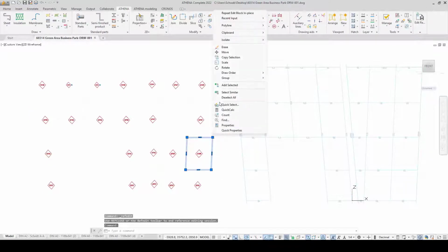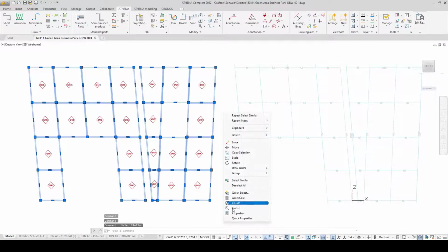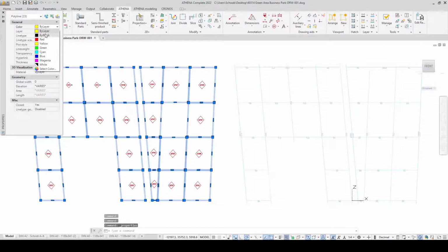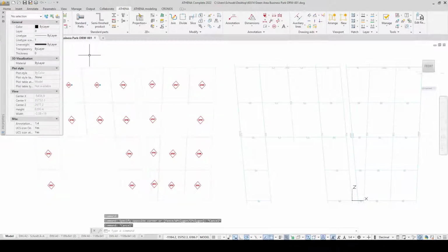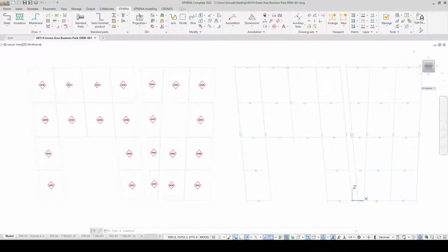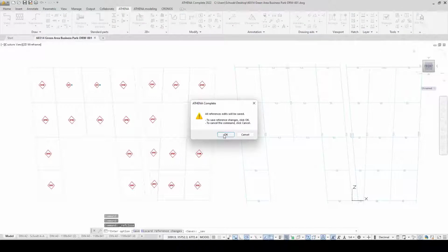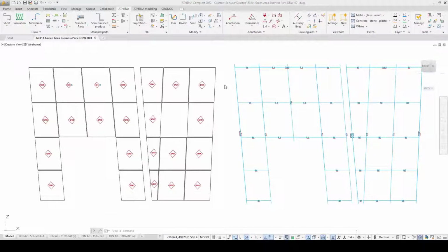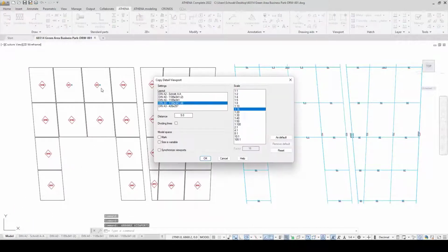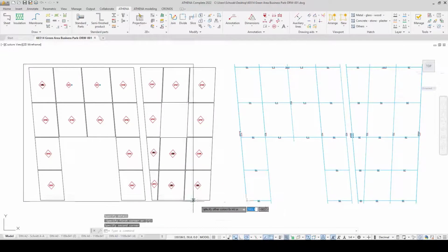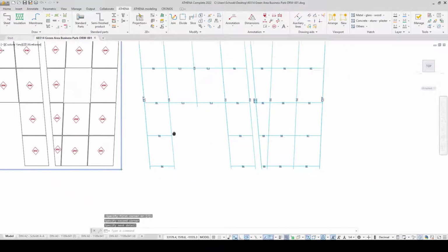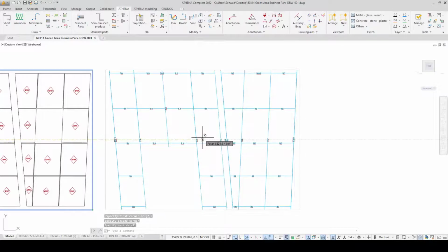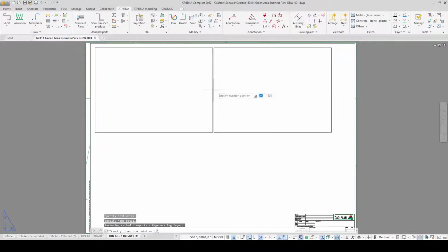With one click you can change the name of your AutoCAD blocks. So now I change the layer, the color yellow on the white background is a little bit inconveniently chosen. And now we can do a viewport arrangement in the scale 1 to 16 to our paper space.